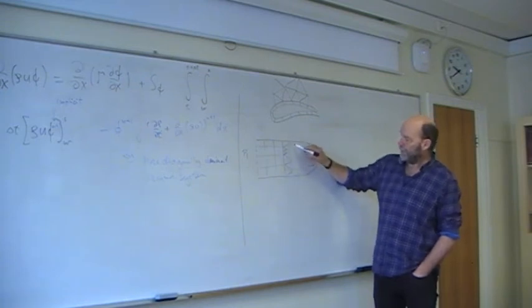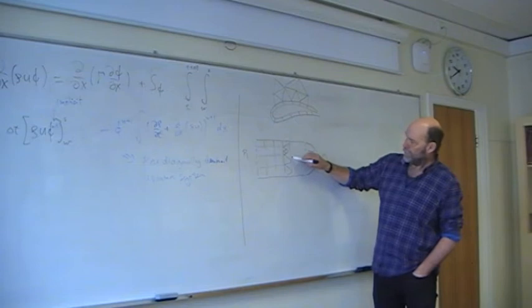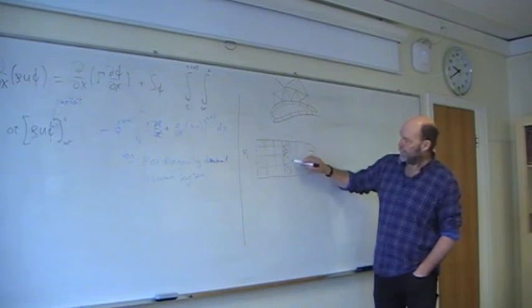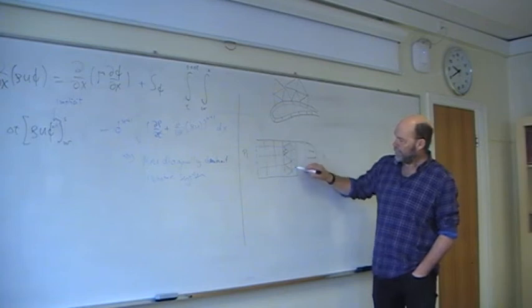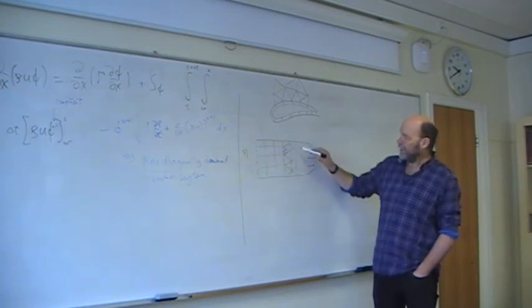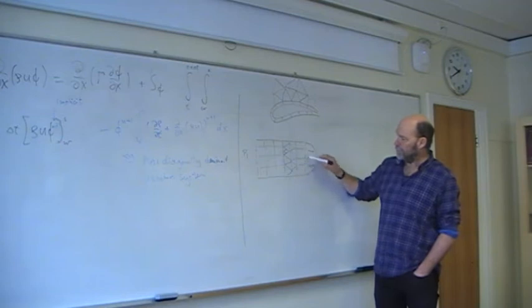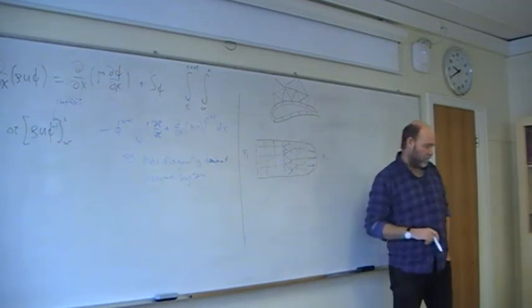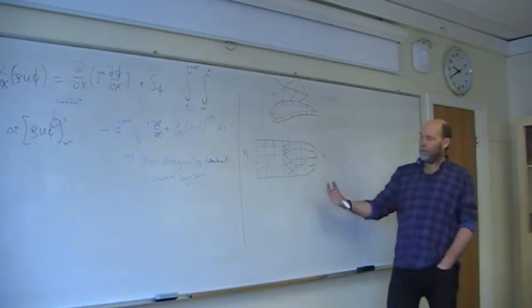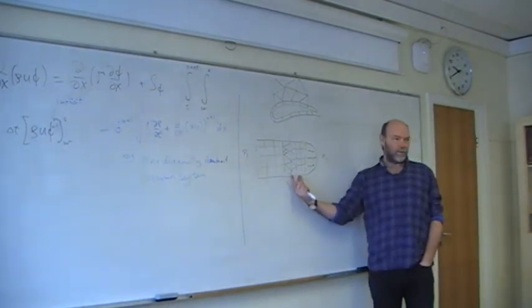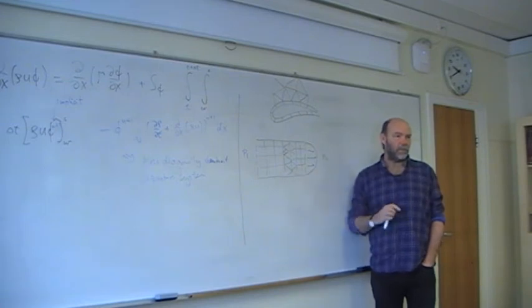And then take another layer here, some triangular systems, and then you go back to the Cartesian. Do that as a test case. Take just a region with totally unstructured mesh, more or less dense. Play around with it, see what happens.